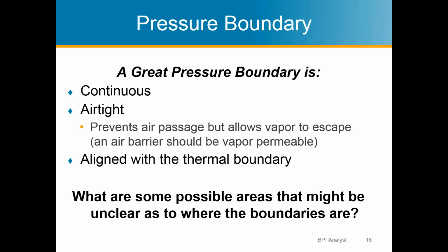And since I mentioned that six-side, what we want for all vertical insulation is 6 sides of contact with the insulation. So in a stud bay, that means the insulation should be touching the top, the bottom, the right side, the left side, the front, the back. That's the 6 sides. That doesn't happen in places like the chimney and the bathtub, and then also knee walls. That's the other place where that's happening.